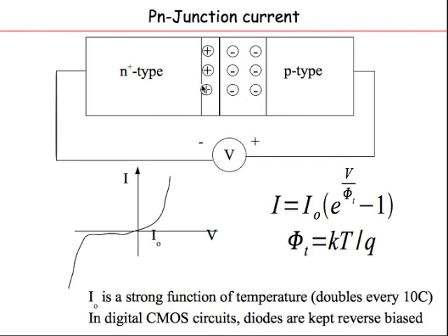Now in this PN junction, when you apply electric potential across it, in the forward bias you have, as you might have all studied in your basic electronics, nothing that you haven't seen before. So essentially there is an exponential increase in the current up to a certain point beyond which the device will break down. Similarly on the reverse bias side, there is not much of a current flow till some point after which there is a breakdown and there is a lot of current.